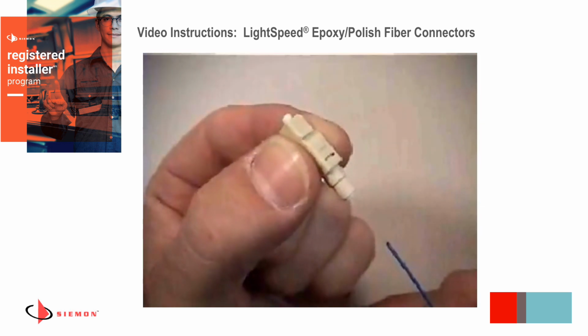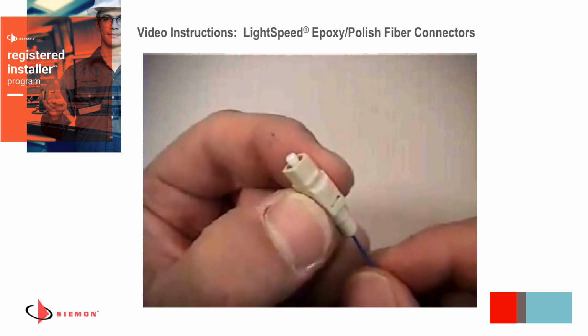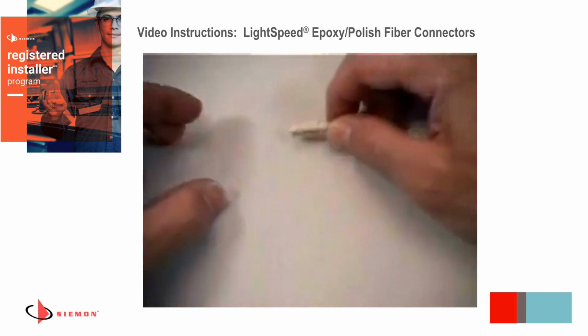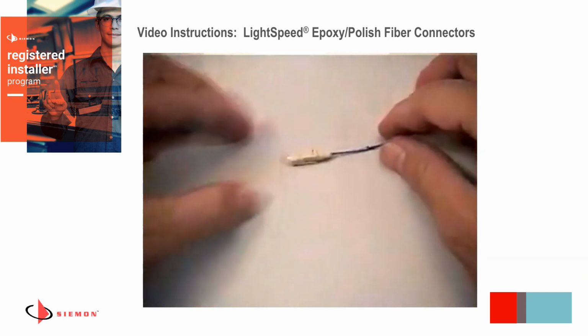Once the primer-coated fiber touches the adhesive, the curing process will start and fiber insertion will become noticeably more difficult if not fully inserted within 10 to 15 seconds. Allow at least 30 seconds cure time before proceeding.